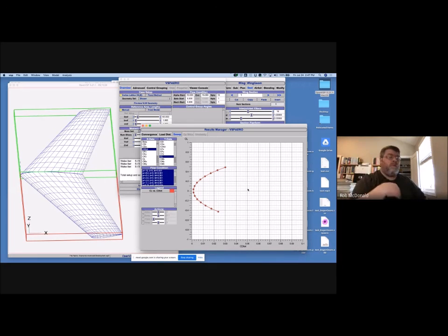But let's say we're patrolling a beach and we're looking for unknown traps. So now my metric is how many miles of beach line can I cover in a certain amount of time, or on a certain amount of charge. If I'm searching for something I don't know where it is, then I probably want to fly at the speed for best range, because my metric is how many miles do I cover. If I can cover more miles of beach, then I want to fly at the speed for best range.